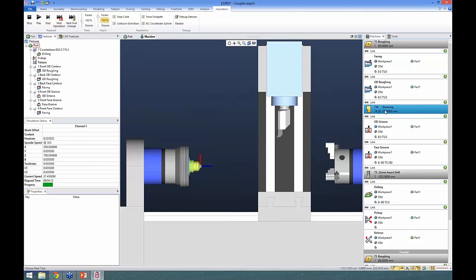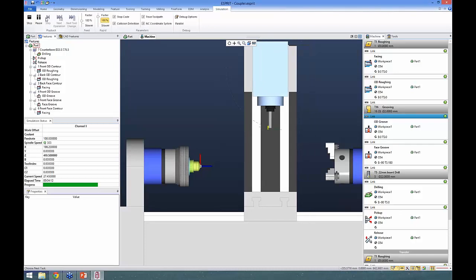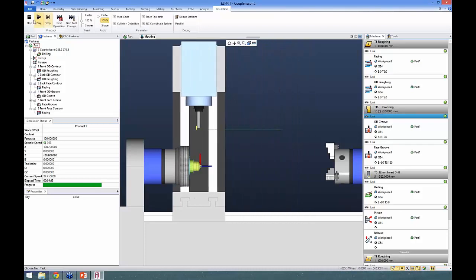So here the link is already over, the tool change sequence starts to happen, we change tools, we have loaded the new tool, and now the new link begins. The link takes care of indexing the tool back to B0, which is the specified rotary axis, and of course we approach the next operation.